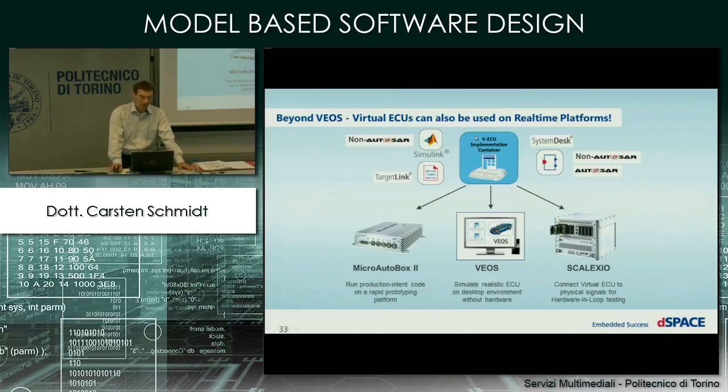For example, we have this prototyping platform, and you can load it to the prototyping platform, and then you have a system that can do real bus communication in real time, basically a kind of physical representation of the ECU, which can be used like a real ECU.